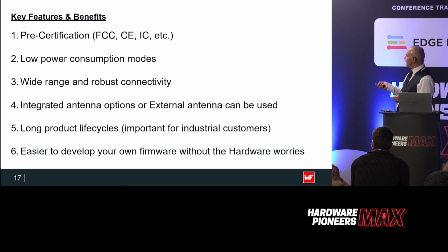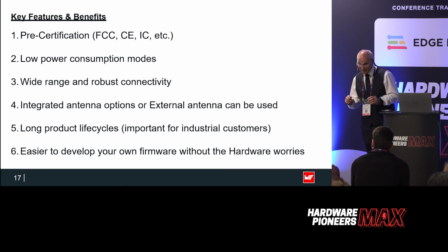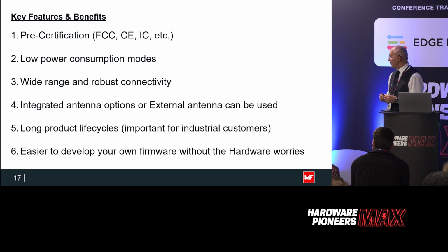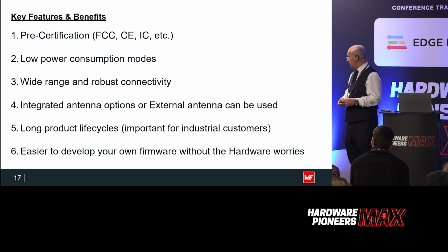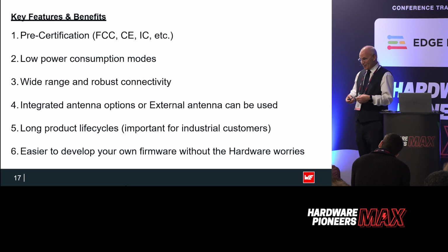So, key features: we do have pre-certified modules, so if you can use a stock firmware, I recommend that you do. It makes life easier. But if you have to use your own custom firmware, because the modules already achieve that level of standard, there's no reason why, if you implement your own firmware correctly, it shouldn't meet that standard. The advantage, again, is lower power consumption. If you don't have to use a separate processor, you can actually achieve a better sleep standard than some of our standard modules, just because we keep certain things awake because we want an interrupt on something.